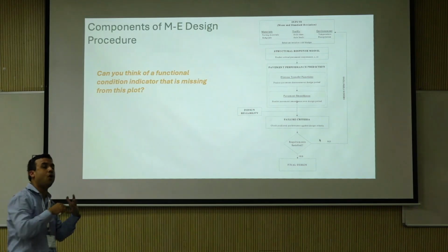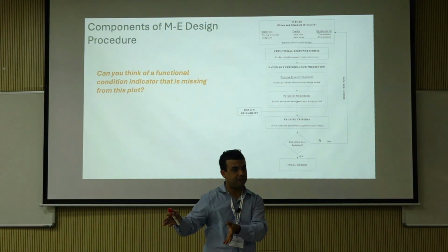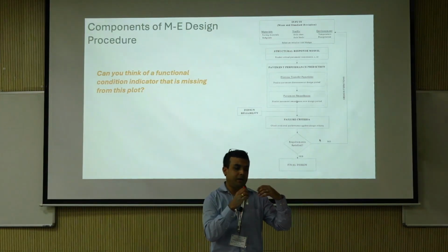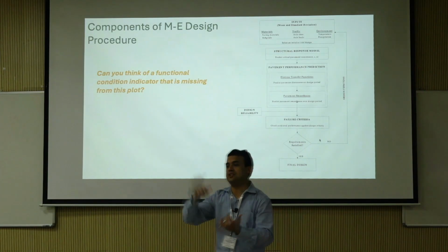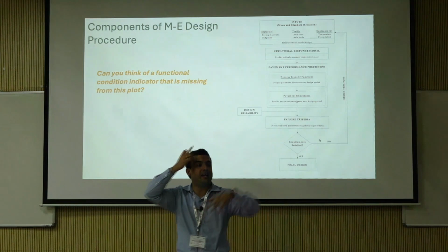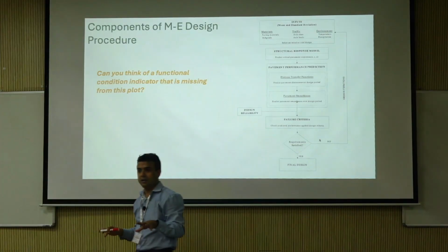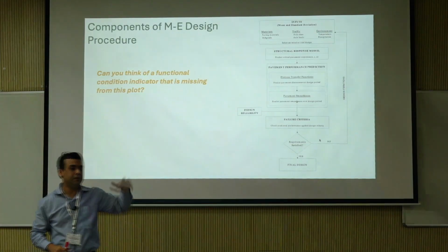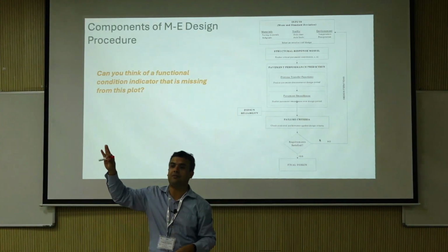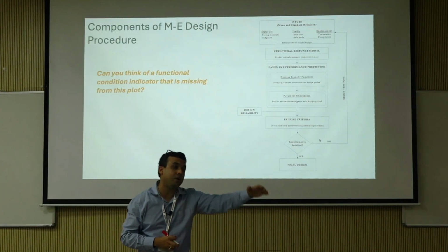And then comes the whole concept of global calibration factors versus local calibration factors. What is a global calibration factor? This much horizontal strain, this much vertical stress leads to this much fatigue cracking on average, when I use national level data to calibrate. Whereas now, because I live in the US, you are in the state of Oklahoma versus Arizona versus Illinois, the soils are different and everything.